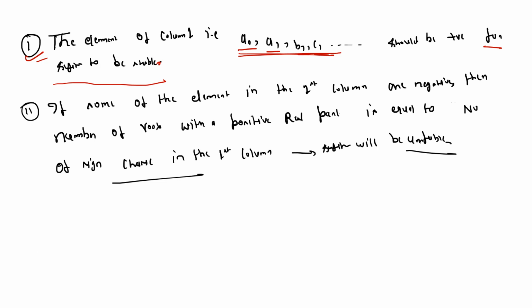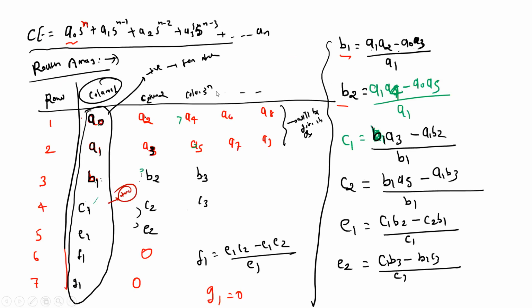We were forming the Routh array and observing the sign of its coefficients, and from there we were telling whether the system is stable or not. It's a very frequent method to analyze the stability of a closed loop transfer function.